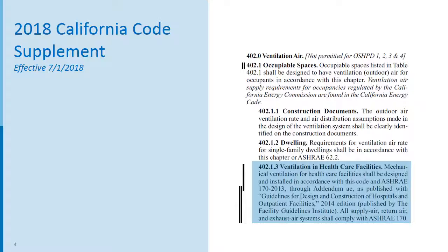And so we had a project team in Northern California where the design engineer saw this in the code and said, well, obviously we need to follow it. And so here's what that means. We need to pull out and replace some fairly new HVAC equipment because we have to put in bigger units. We're going to need to add some return ducts and controls to meet some of the pressure requirements. We need to plan on about double the energy consumption as an operating cost. And we would actually need to write a variance from the AHJ to exempt us from following the energy code.